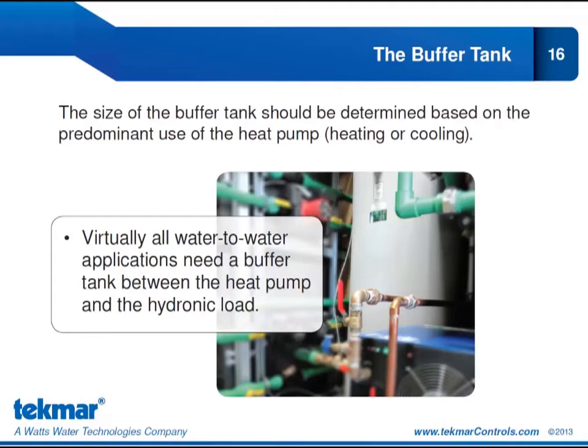Now, the reason it's so important to size that buffer tank appropriately is to prevent equipment short cycling. It also allows us to have different flow rates through the heat pump than through the distribution side. So we get that hydraulic separation with the use of the buffer tank. Now, the heat pump usually needs a much higher water flow rate than the hydronic load, so operating without a buffer tank can cause refrigeration circuit problems. So we can avoid all of that by including the buffer tank, and that will save our heat pump from cycling on and off, and it will give us the hydraulic separation that we need.